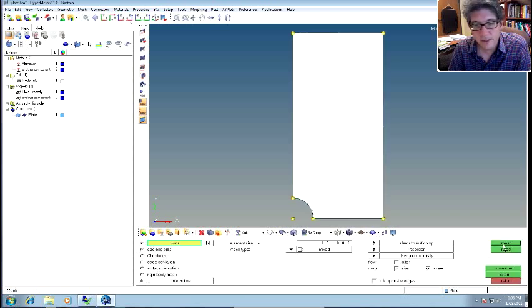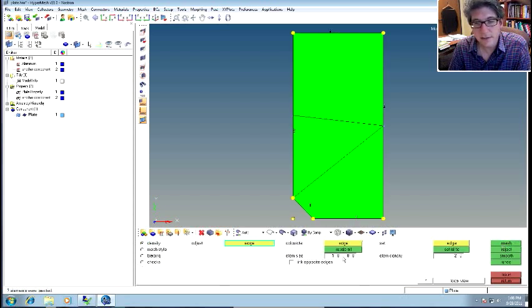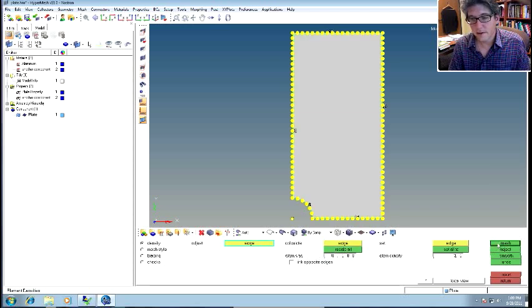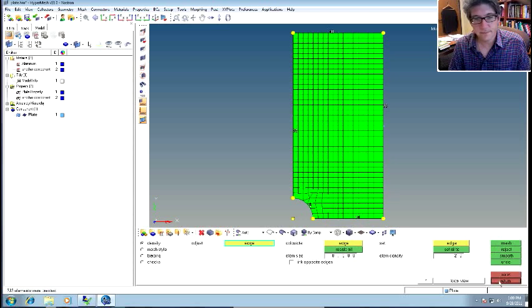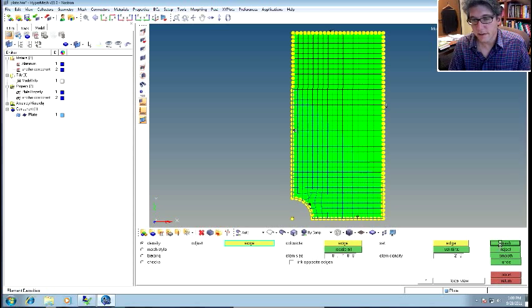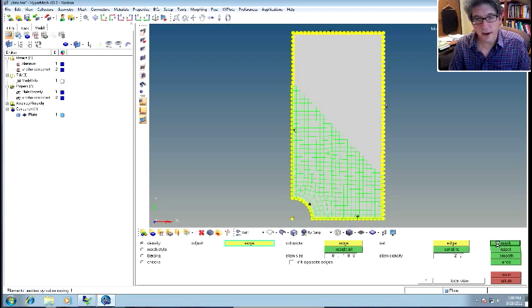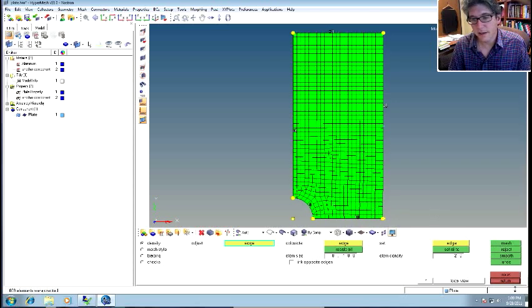And that'll mesh. And you can see here I have the same option, so let's set it to like 0.5. We'll recalculate all the 0.5. And now you can see I'll probably get a nice, good mesh. I can even set them all to 0.4. It's not that bad in the sense that it's still not millions and millions of elements.